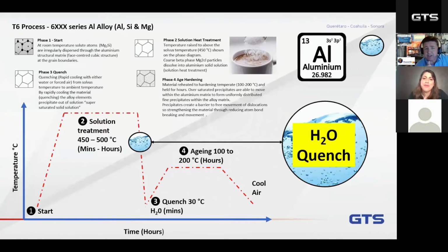Obviously, the challenges for this particular process are, firstly, that we have to provide thermal protection in the first part of the process, which is the furnace, typically up to 500 degrees for a number of hours. And when we're talking about 3, 4, 5 hours, you need a thermal barrier with some significant insulative behavior to give you the protection of the data logger.